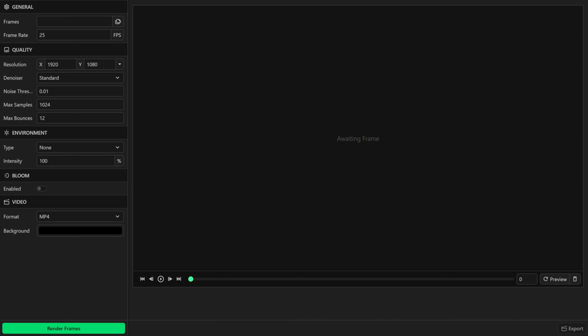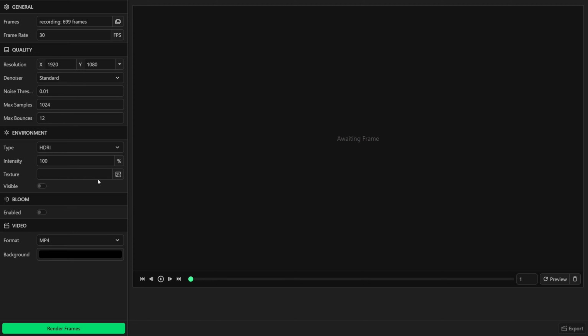All right, now that we have ProtoTwin Radiant open, I'll give you a quick tour of the UI. We first need to import the zip file of frames that we saved out for the recording into the tool. You can change the resolution for the recording or select one of our preset resolutions from the drop-down list. It is also possible to import a HDRI environment map into the tool. You just need to click the Import Texture button and then select a HDR file from your local drive.